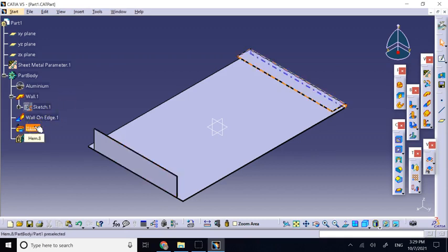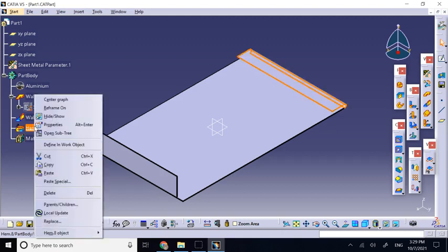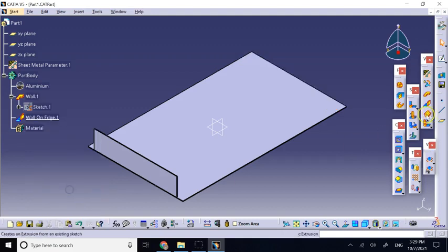The matter of fact is, when you work with sheet metals, when you form such an edge, a vertical edge, let's say by forming two, as I said, flanges, there is a good chance that you have tear in the sheet metal due to the bending stress at that corner. Because corners are going to be at that location a sharp spot with a lot of stress concentration.